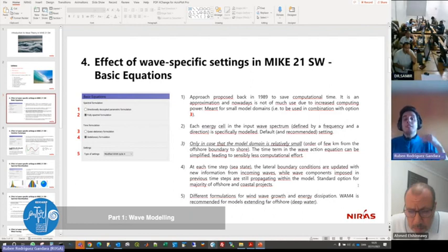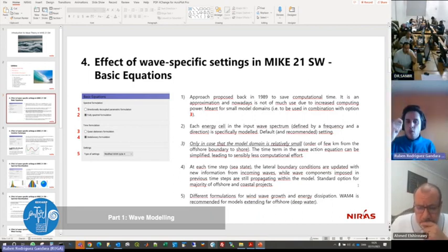So these are the waves that you're going to impose at the boundary of Mike in order to transform those waves to nearshore. And in there, you have to take a look at all the wave periods. You can take a look at the peak period. You take a look at all the peak periods that you are going to simulate. Okay, so one time step will have a peak period of 10 seconds, another one of 12, another one of 7. And then with that period, what you can calculate is very quickly.